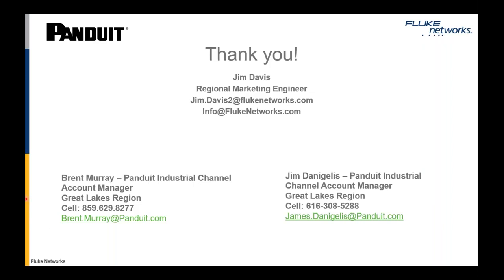So it's got 2-pair cable and 4 conductors, right? And so it also has Category 5E performance, and it's associated with using the cabling for a smart block type application or a smart IO application. So the D code M12 is used for that purpose.